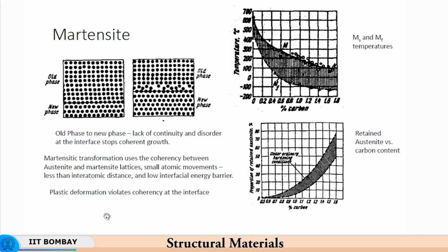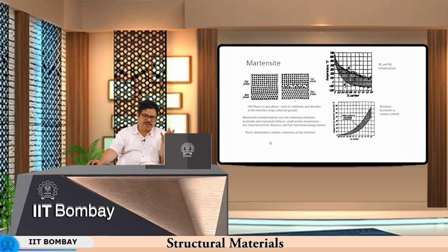For cold working dies, let us say press working dies for example, or blanking dies, there you would like everything to become martensite. So, cryogenic treatment especially for cutting dies or cutting tools would be in order, because you want essentially to carry out a separating process, meaning you want to separate out some material from the main chunk of material, for which addition of a large percentage of carbon and then doing cryogenic treatment will result in a very high hardness, giving you a very high level of material property.